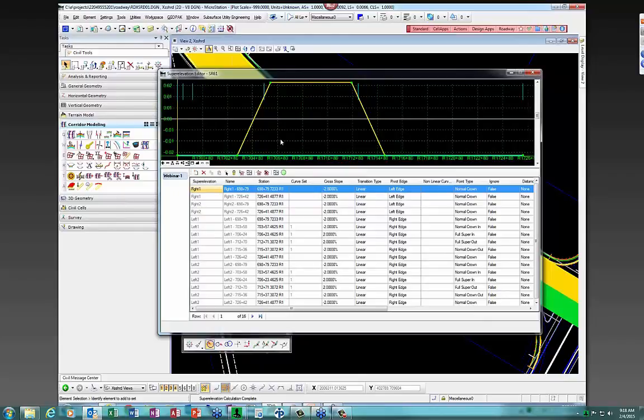This is similar to the quarter modeling super elevation diagram that you got in SS2. And now this has been added. This is a list of each of the controls. So everything that's right 1 is the right 1 control line. Right 2 is the right 2 control line. There's more entries for the left lane because it's the one that's actually having to rotate up, whereas the right lane is going to stay right there at 2% for that particular design speed. Okay, and then you can close this,